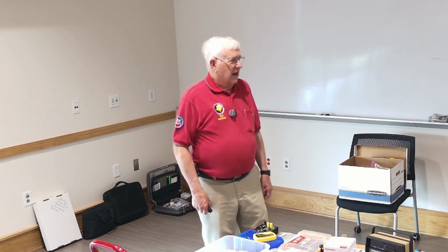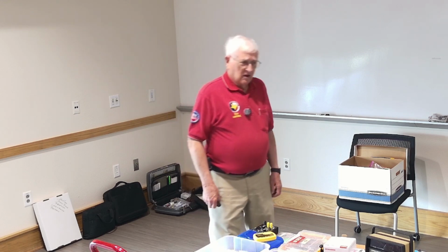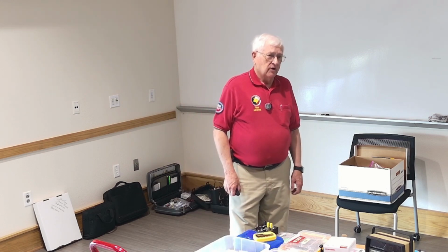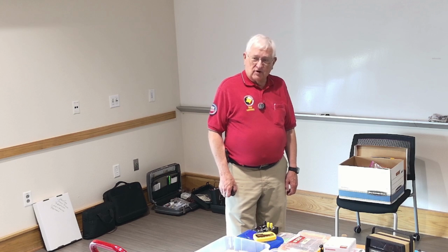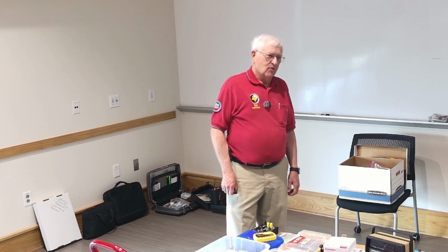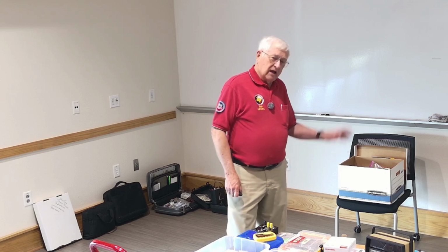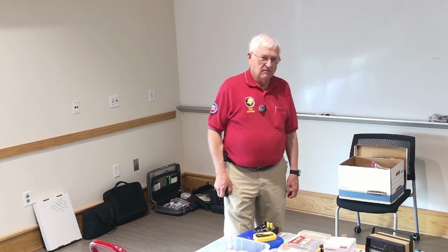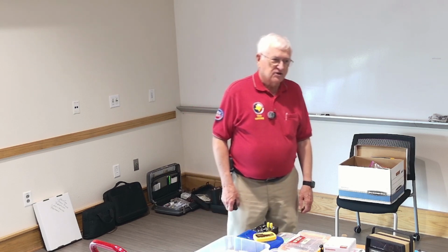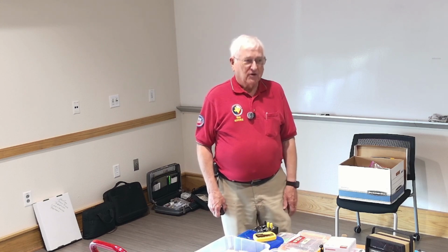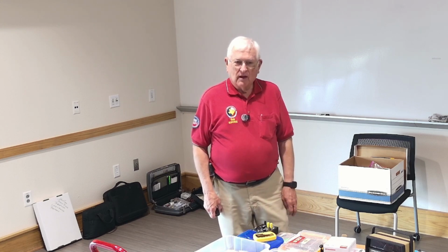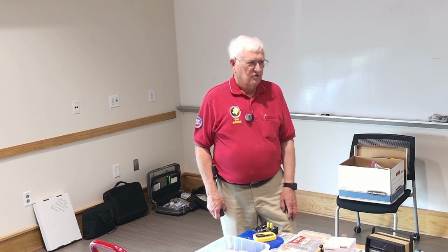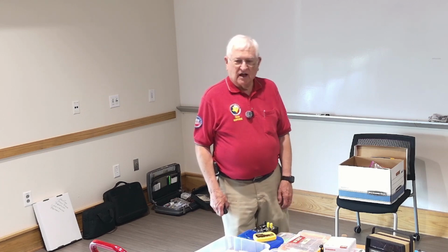Now, all of these instruments, by the way, can be calibrated so that they're accurate. But you have to have a standard by which to calibrate them before you can do that. In my case, for the frequency, I'm very fortunate. I have a cesium beam standard, which is good to 10 to the minus 13. That's accurate. That's very, very accurate. It generates a 10 megahertz square wave signal, and I use that to calibrate my frequency counter.